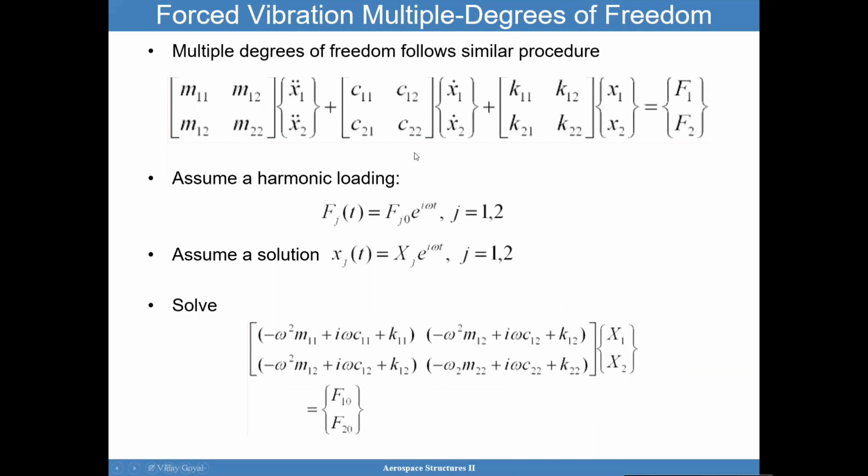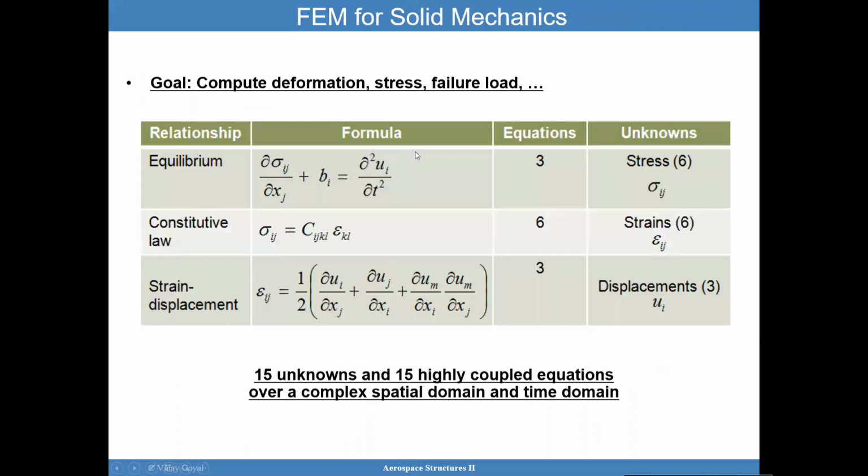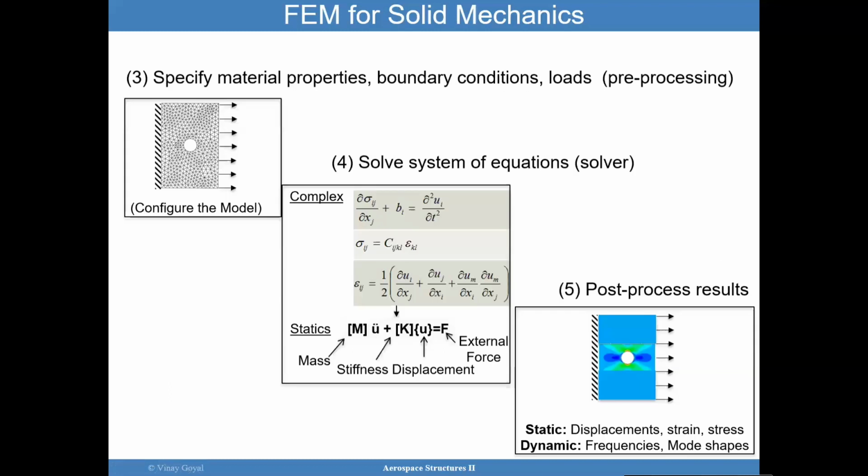And here I have damping, and we can add that here, but the bottom line is that it's a mathematical miracle, because I took 15 equations that are highly coupled and turned them into a matrix of mass, stiffness, and a vector of deflections and a vector of accelerations equal to a vector of external forces applied. So this is huge progress that we made here.